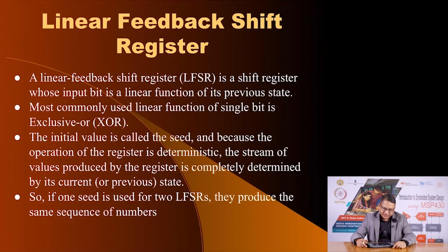Now, a linear feedback shift register is a shift register. Basically, it is a whole bunch of D type flip flops, where the output of one feeds the input of the second and so on, and then the last one is fed back into the input. Of course, you do not just connect it like that, you operate on the outputs in some way, and the linear function could be through an XOR or an XNOR gate. Because these are flip flops, you need to initialize them with some value when you turn the power on, and that value is called the seed value.